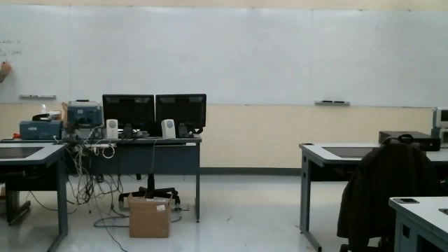So that becomes I over sigma S 2 pi L times the natural log of A minus the natural log of B. I'm going to get rid of the minus sign by incorporating it, so it would be the natural log of B minus the natural log of A. But the difference of natural logs is just the ratio of the two arguments.